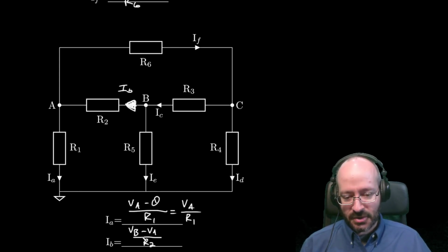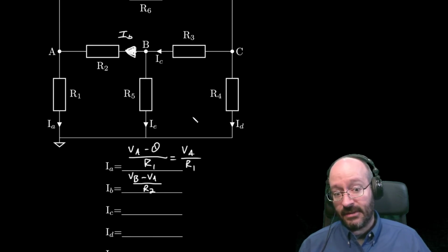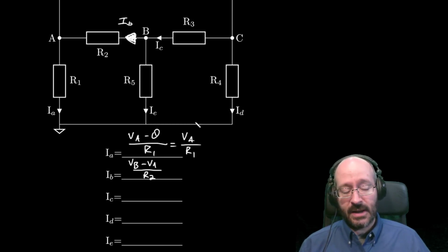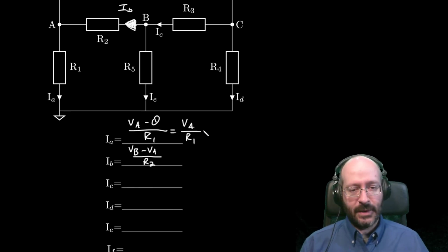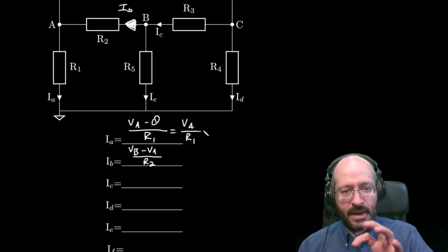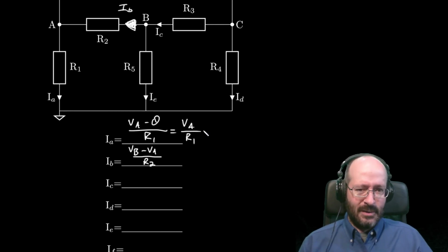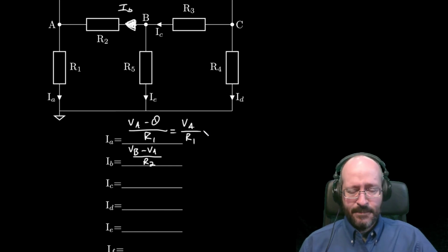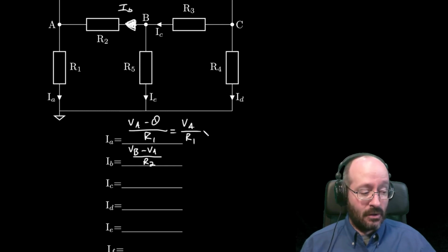While I switch the direction, VA becomes negative, VB becomes positive, and we can see that's the opposite of what we had up here. So we're going to get the opposite sign. The signs are important. Keeping track of them is important, just like it was in mesh analysis. So we've got to get this right. I hope that these last two videos have given you the basic techniques that I use, the things that go through my head when I'm writing these equations for getting the signs correct.